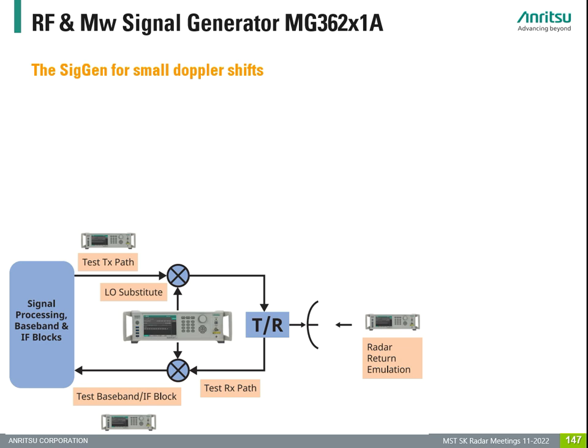Pulse Doppler radars combine all the benefits of long range and high velocity capability. Pulse Doppler radars use a medium to a high PRF in the range of 3 to 30 kHz, which allows for the detection of either high speed targets or high resolution velocity measurements. Normally, it is one or the other. A radar designed for detecting targets from 0 to Mach 2 does not have a high resolution in speed, whereas a radar designed for high speed velocity measurements does not have a wide range of speeds.